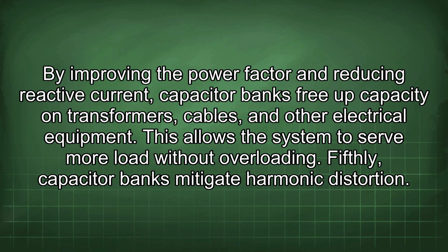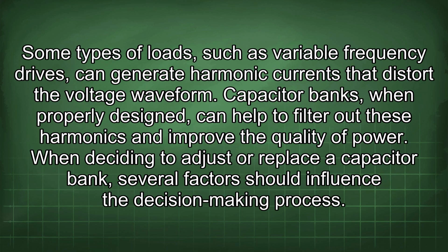Fifthly, capacitor banks mitigate harmonic distortion. Some types of loads, such as variable frequency drives, can generate harmonic currents that distort the voltage waveform. Capacitor banks, when properly designed, can help to filter out these harmonics and improve the quality of power.